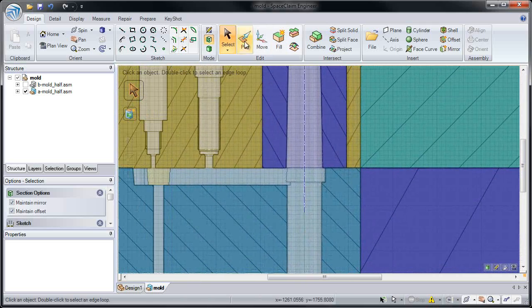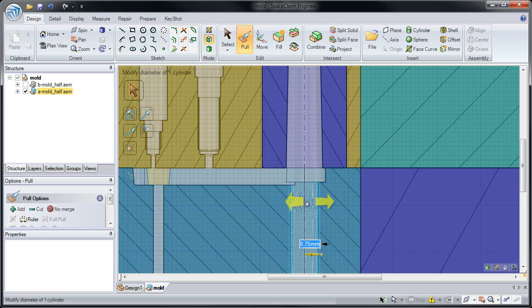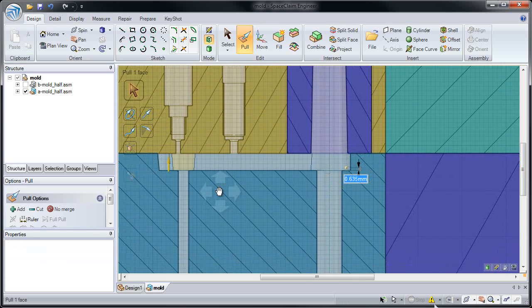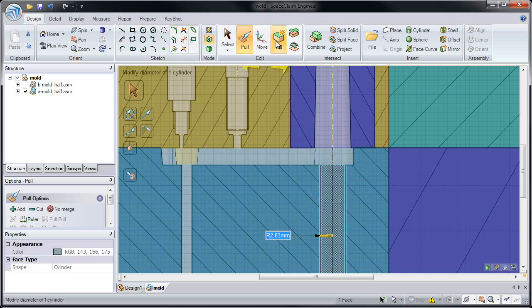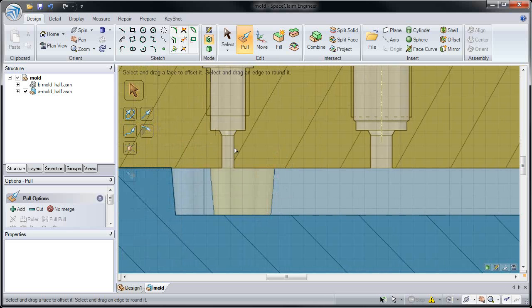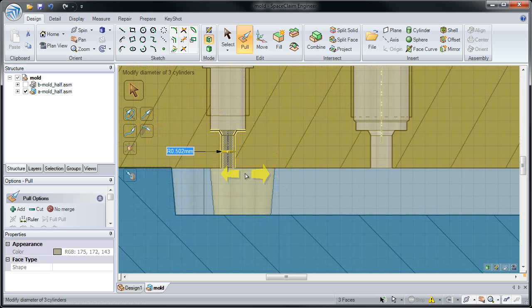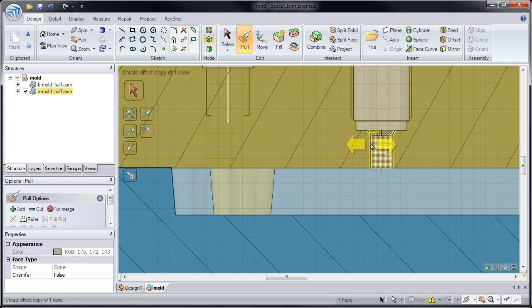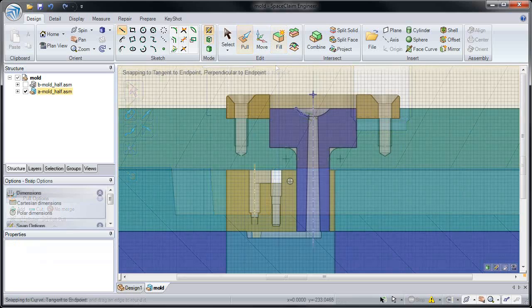Now we've seen editing models in 3D, we can also make dynamic changes in a 2D cross-section, pulling on faces, pulling on holes, or snapping them to the same height. Now if we're going to go back and extract our volume later on, it might be helpful for us to fill geometry in, removing holes, just with a click of a button. And seeing them in this cross-section makes it much easier for us to select them.